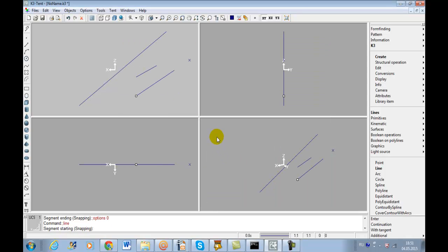Okay. There are also some object snaps that are not precise. These allow us to snap to arbitrary points along an object. These would include nearest, tangents, and perpendicular, and to some extent intersection, and so on. For example, perpendicular.